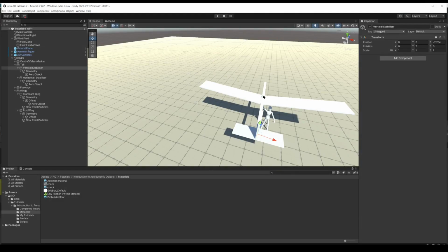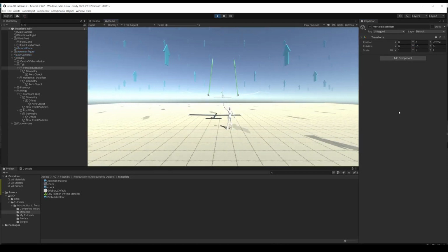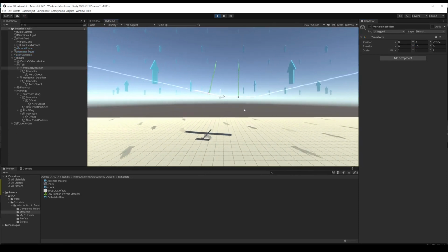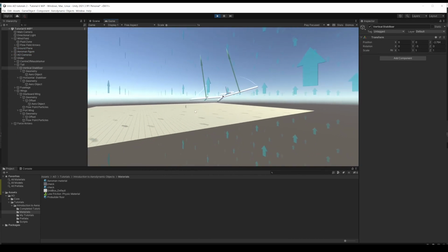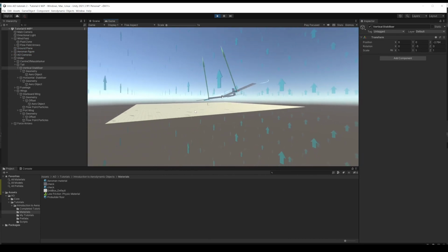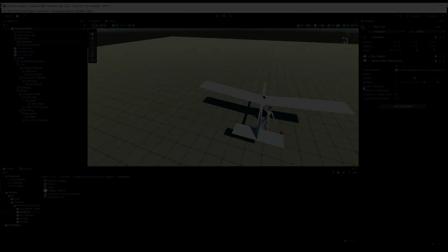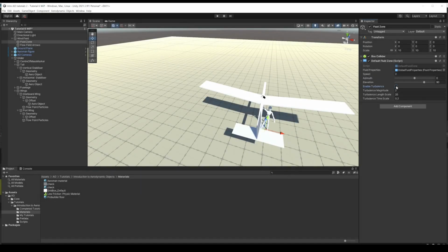Fantastic. Just to show we know what we're doing, let's change the fin angle to the other way. Let's put it at -5, so it's a slightly more gradual turn, and let's see what that does. So yeah, we're turning to the right. Okay, so we've just seen what happens when you vary the trim of the aircraft.